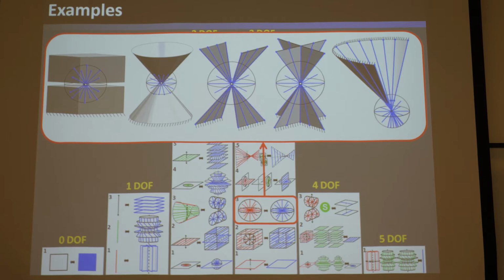Okay, and again, this is just approximate. To be really accurate, you'd want basically a shape like this: two opposing cones that just touch right at their tip, and then are short. That kind of approximates a nub flexure here. But this one's a little clearer. Of course, the diameter there would need to be infinitely thin to be super accurate. Okay, but this is approximate, right?